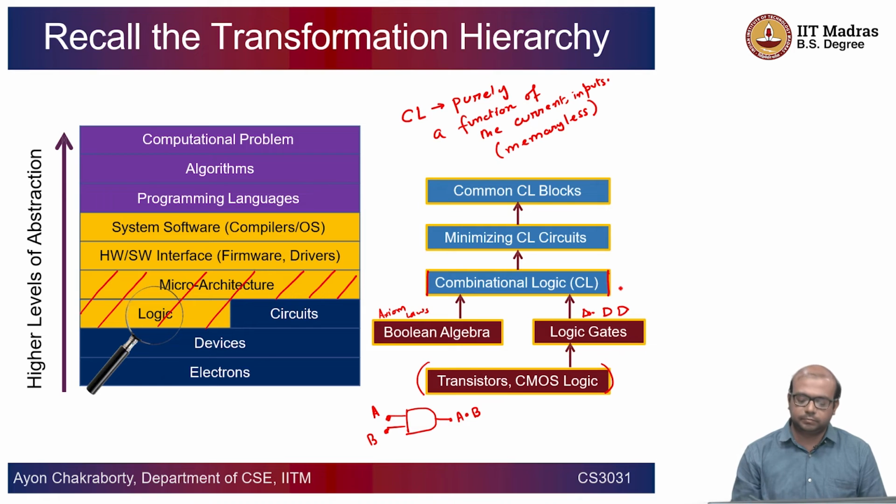Given a circuit or a huge truth table that gives you the functional specification of the circuit, one idea is to simply convert that into some kind of logical expression and build a circuit for it, right? However, there might be room for improvement to minimize the cost of the circuit or to reduce the form factor of the circuit by using a lesser number of gates.